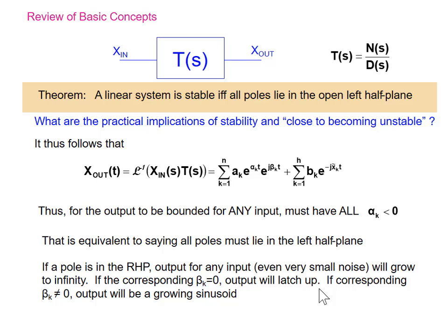And occasionally what you will have is feedback in that operational amplifier that will cause that nonlinear system to do one of two things. It will break into some form of oscillation, oftentimes non-sinusoidal, or the output will just get stuck at some point. Completely unpredictable by the small signal model. You're not a good op-amp designer if you design circuits that have that problem.